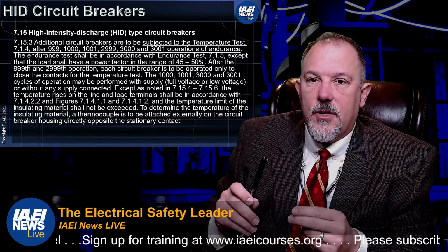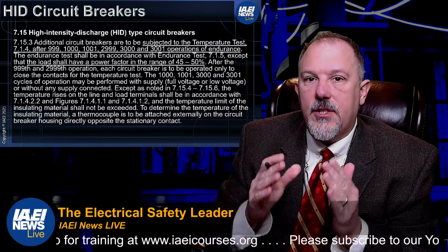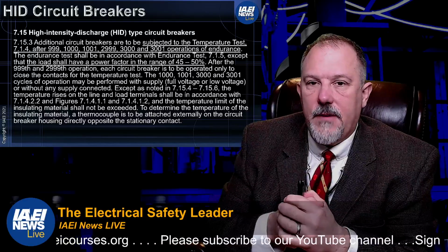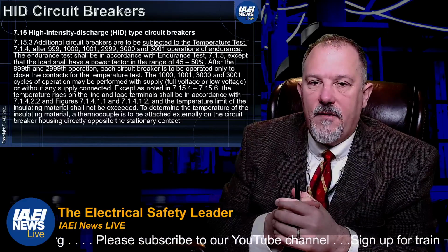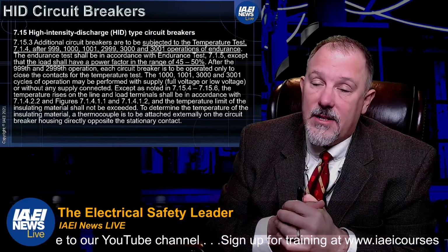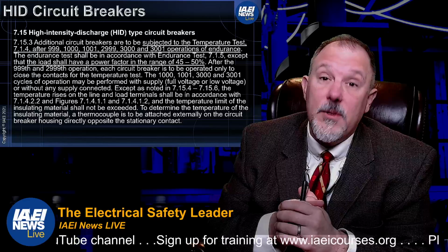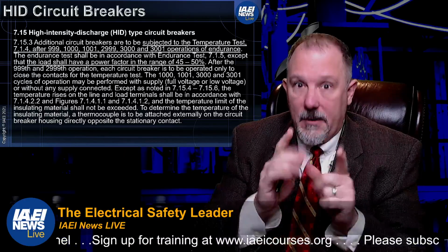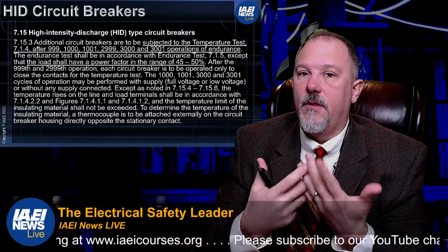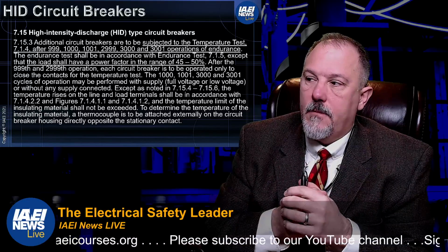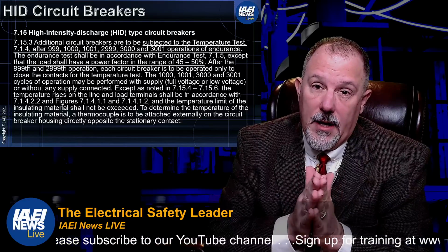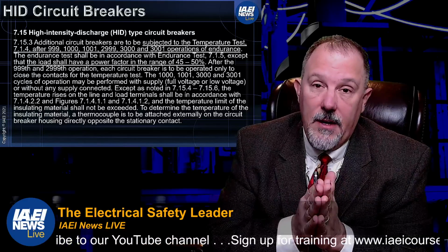So when the power factor, the hardest time for a circuit breaker to stop that flow of current while we're opening and closing those devices is when the power factor is low, like 45 to 50%. Lower than that, it gets very difficult for the circuit breaker to do its job. And think about what happens. You're drawing an arc. It's going to be probably a little bit more violent. And the contacts of that circuit breaker need to be able to handle the exposure that we're giving it.